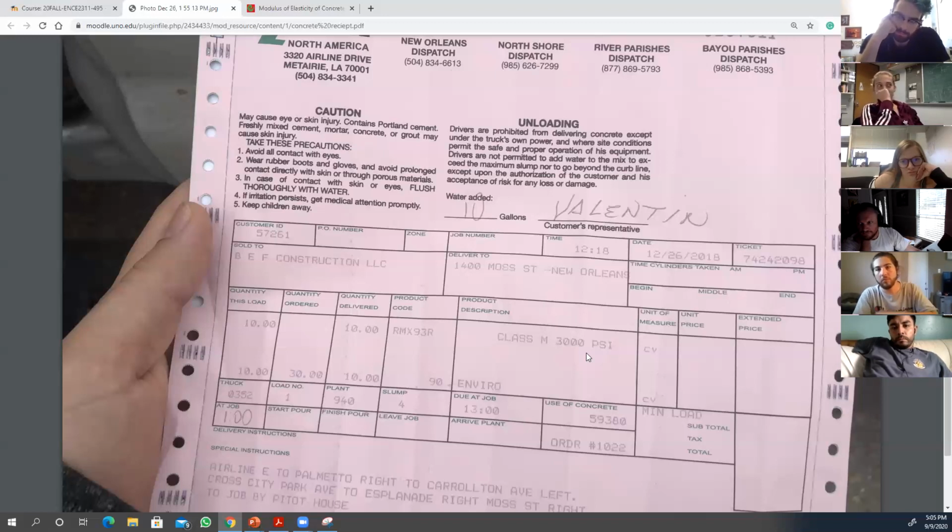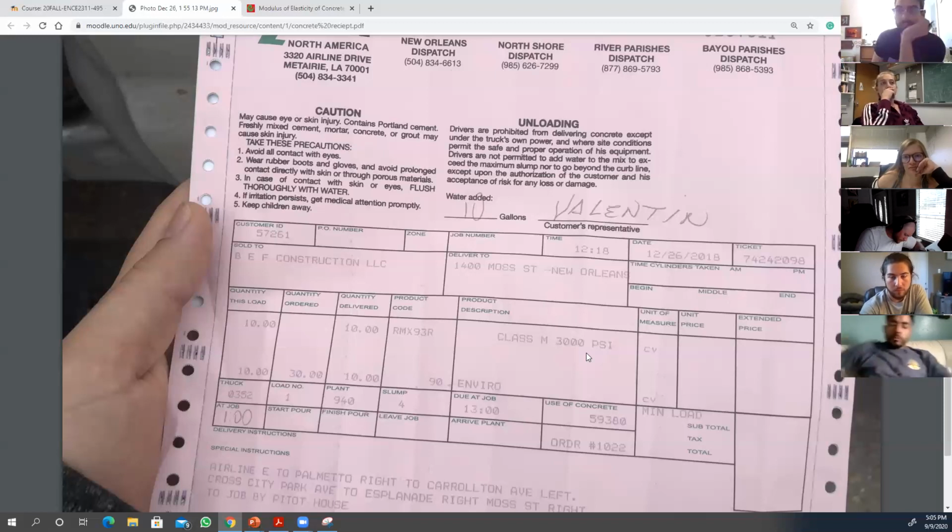If the slump is okay, you proceed and you start pouring your concrete. But in the meantime, from that first batch, you take samples into cylinders. I have my cylinders, 3 of them, on job site. I take my samples, 2 samples, and I take it to the lab. Not me, but the inspection company.